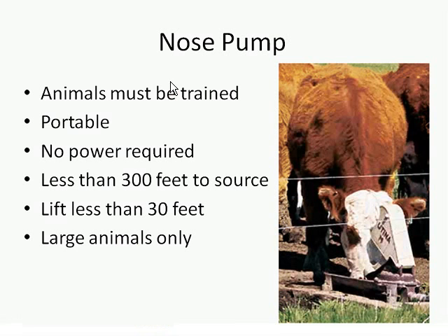They basically pump this pump that pulls water. It's limited in how far it will lift water. It can lift water about 300 feet, and typically you need to be fairly close to your source. And these kinds of systems only work with large animals.